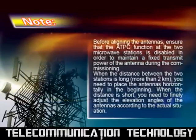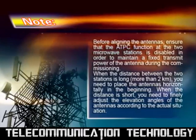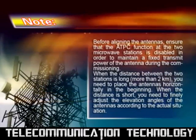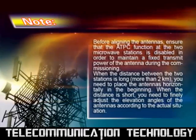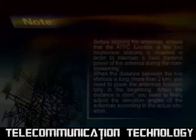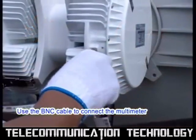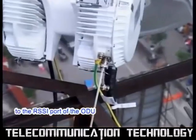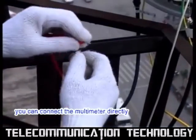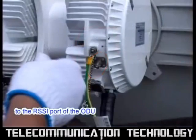When the distance between the two stations is long, more than 2 kilometers, you need to place the antennas horizontally in the beginning. When the distance is short, you need to finally adjust the elevation angles of the antennas according to the actual situation. How to align the antennas? 1. Use the BNC cable to connect the multimeter to the RSSI port of the ODU. If there is no BNC cable, you can connect the multimeter directly to the RSSI port of the ODU.